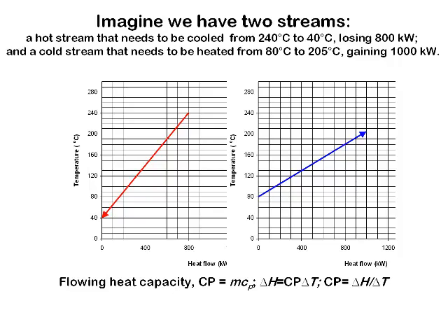If you had a larger mass flow rate for a given amount of heat input, you're trying to heat more material, so the temperature rise that you get isn't going to be so great. Similarly, if it has a larger specific heat capacity, that means it's able to hold a lot of heat without changing its temperature much. So a larger specific heat capacity would also have the effect of giving a smaller temperature rise for a given amount of heat input.